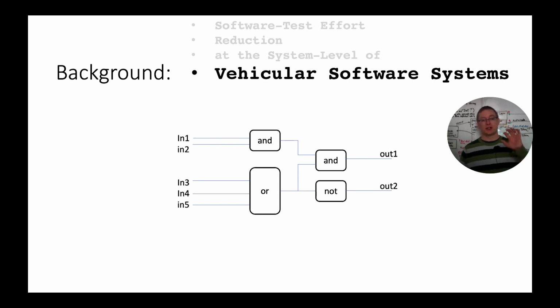From each sensor you can read a signal. It could be a continuous value, or it could be a binary value, on or off, but it's all about the signals. And to the left you see they have 5 signals coming into the program, and these are read at the same time in a cyclic fashion, like every 64 milliseconds.